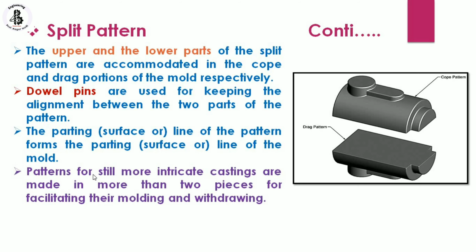So just you can see the first figure. That will be the cope part, and these are hatch sections, that will be our pattern. As per my requirements, you can see some loose pieces being fixed with the pattern. Just you can see in the second figure, figure A, that will be the pattern. You can see such kinds of slots on the pattern, which will have difficulties for removal when making a mold cavity.